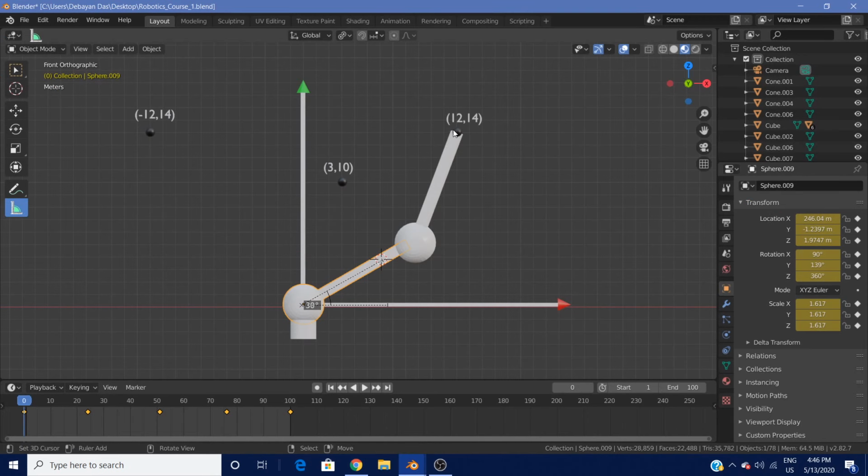And this is the task space trajectory that we have to follow. This is the actual trajectory that we have to follow. And we're going to define theta only for this particular link. Of course, we could have a theta for this link as well, and we would need it while actually programming. But for the sake of this course, and because we don't have much time, we're going to deal with theta of this particular link only. So we are looking at this theta from this frame to this frame.